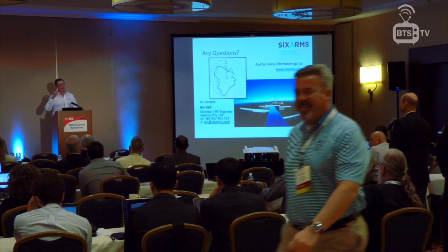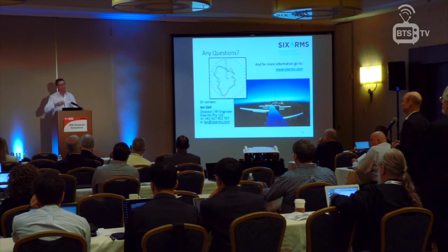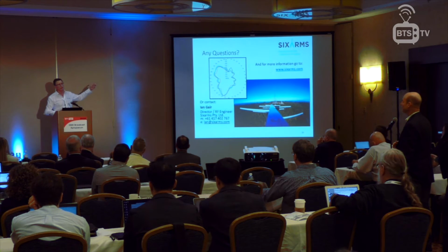Yeah, so it varies depending on what the receive antenna is, and that comes back to the accuracy table that I showed. If you want a more accurate result, you can pin those down so that instead of having a beam width of, for instance, plus or minus 3 dB, you bring the beam width right down to plus or minus a couple of degrees, and therefore the magnitude of error that we quote will be a much tighter tolerance.